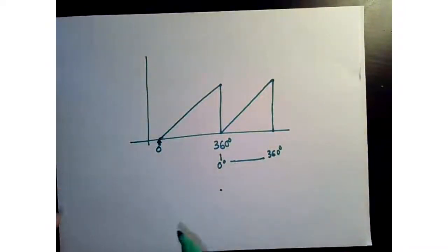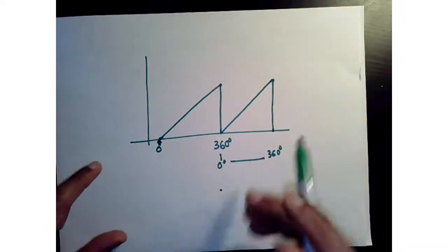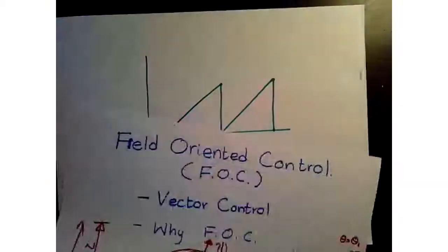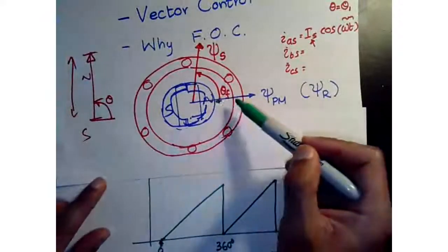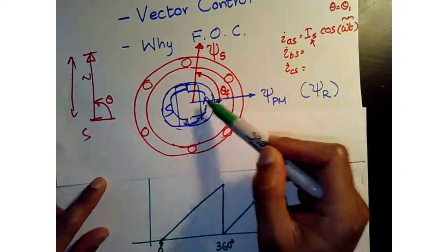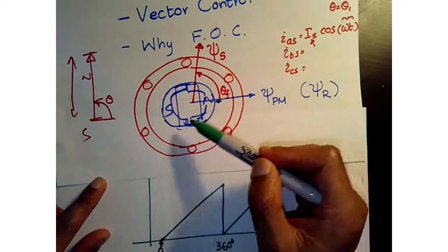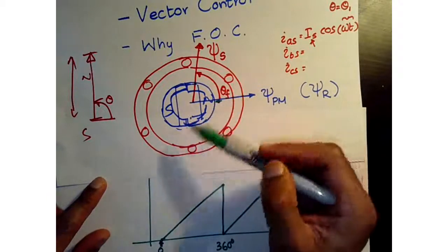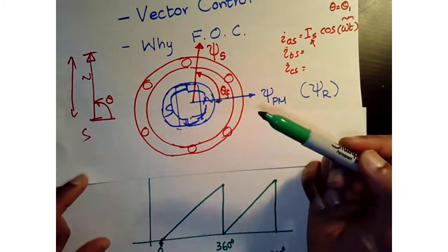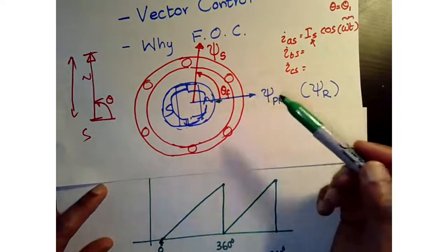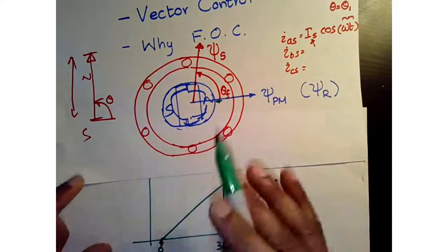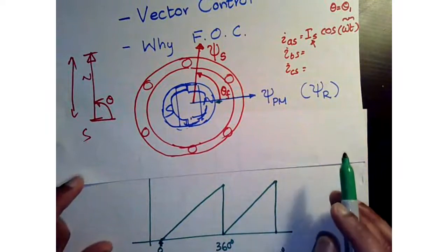Now, practically speaking, aligning the sensor zero with the rotor flux zero is a very difficult task, because you have to look at back EMF, and most of the time you have line-to-line voltage, and you have to offset by a certain amount depending on the number of poles. So it becomes a tedious process.